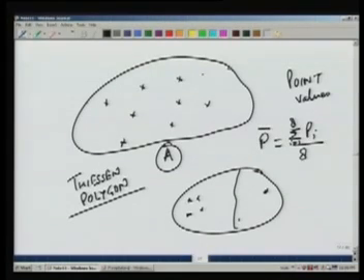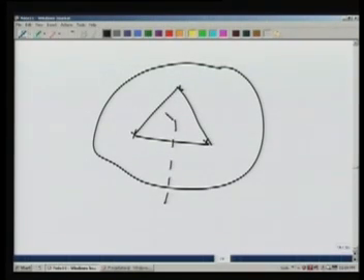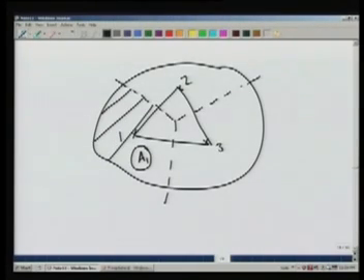In which the relative position of the various gauges is also considered. So if we have rain gauges in an area like this, we draw perpendicular bisectors of the lines joining the rain gauges, and then we assign, suppose this is rain gauge 1, 2 and 3, we say that area A1 is the effective area for rain gauge 1. Similarly, area 2 and area 3. And then when we compute the average precipitation, we give weight to individual rain gauges.